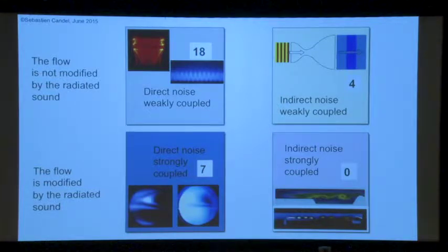These go into the nozzle and they give a pressure field. This is a topic of my thesis. I studied that with my advisor, Frank Marble. There is a famous paper of ours, which is well cited, which explains indirect noise. This is another source of noise. You take temperature fluctuations, pass them through a nozzle, and it produces pressure fluctuations. When we did this work, it was not known, and it has since been named indirect noise or entropy noise.